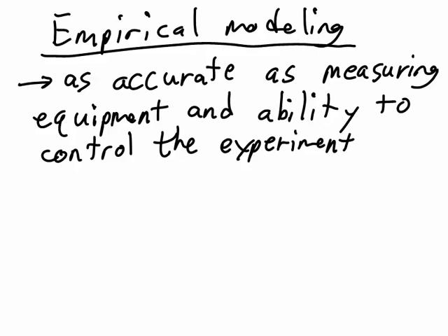We could only approximate the system behavior. We could see from the response whether the system was first order or second order, but we had difficulty getting accurate measurements for the time constant, the damping ratio, and the natural frequency. We also used the empirical method to model the motorized potentiometer slider. In that lab, we used an oscilloscope to measure, and we used a function generator to control the input, so our results of modeling were better.